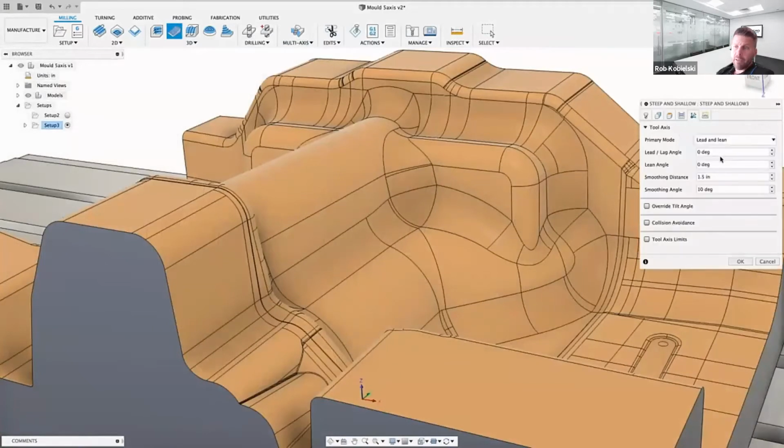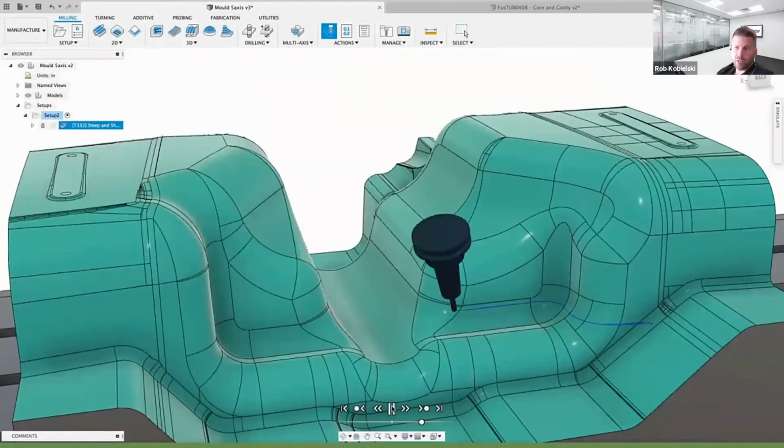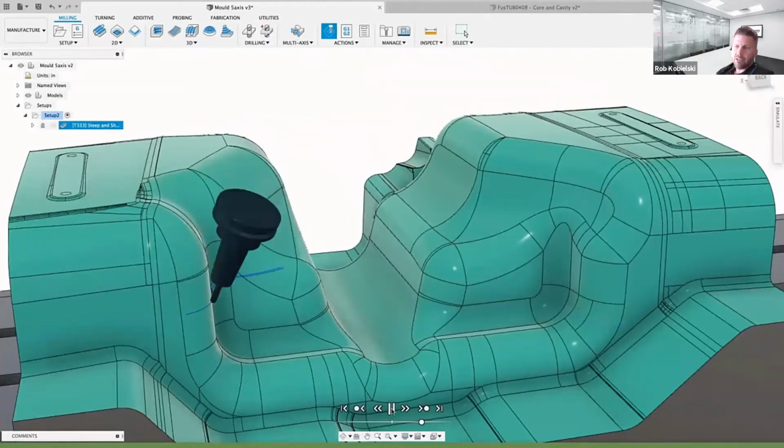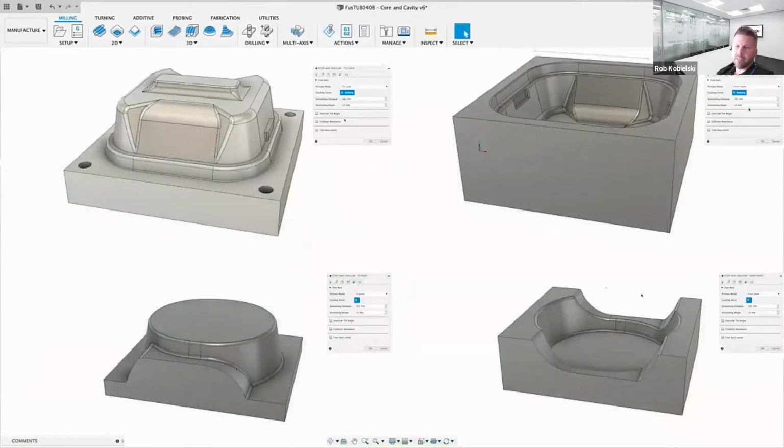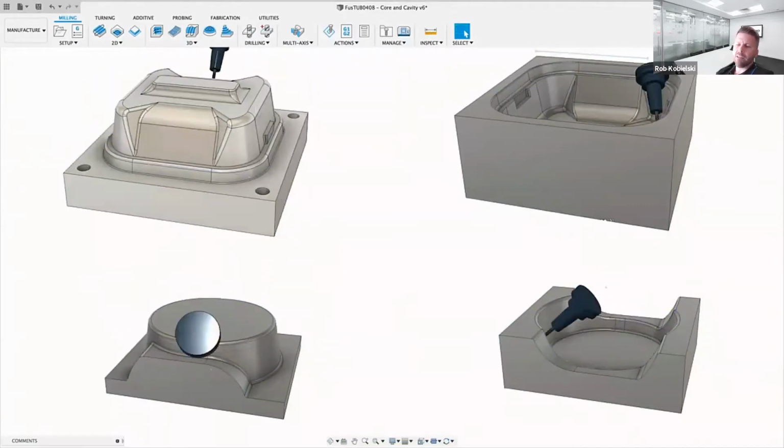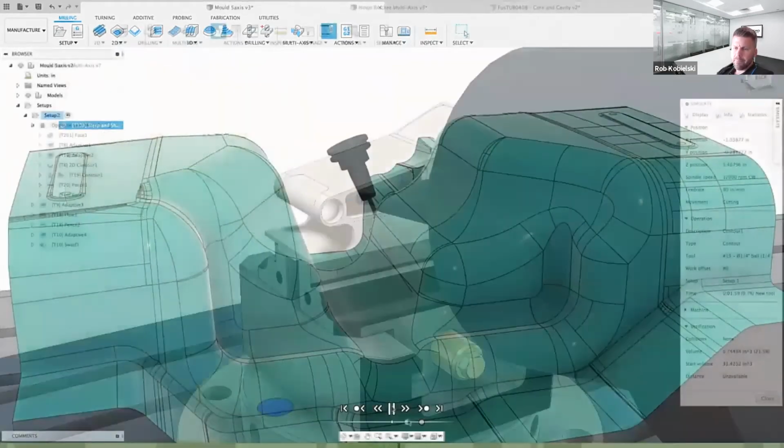For the most complex parts, there's a full simultaneous 5-axis programming to allow the use of shorter tools, which are more rigid and reduce vibration, that ultimately improve the surface quality of finishing operations. A selection of toolpath options are available as well, with a range of tilting methods to improve surface finish, as well as the ability to cut with the side of a tool to take advantage of its entire flute length.